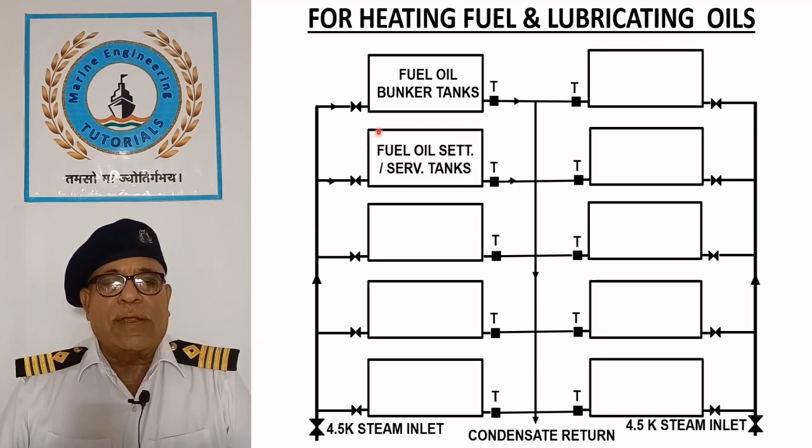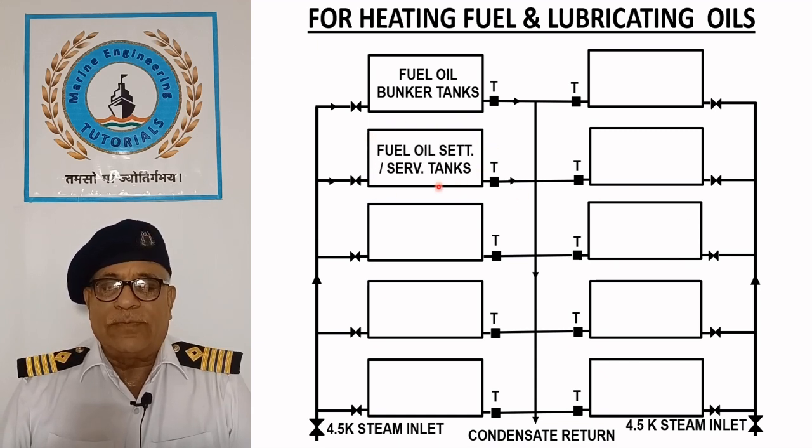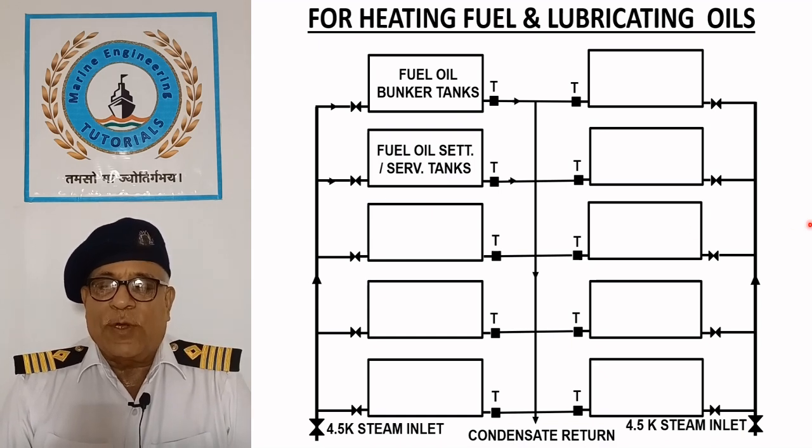Fuel oil settling and service tanks. When heavy fuel oil is transferred to the settling tank, it is heated to approximately 75 degrees Celsius to promote separation and removal of water. After purification, the fuel is stored in the service tank, where the temperature is maintained prior to its use in the engine.